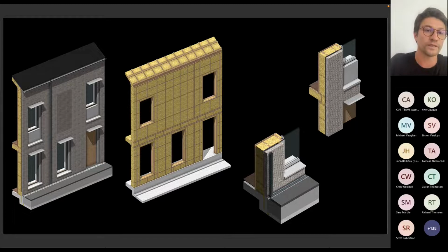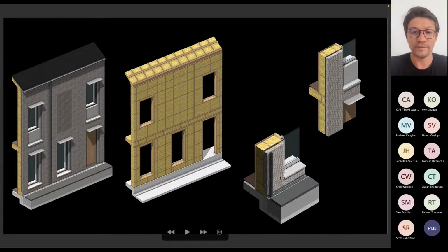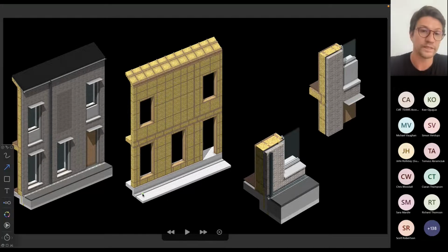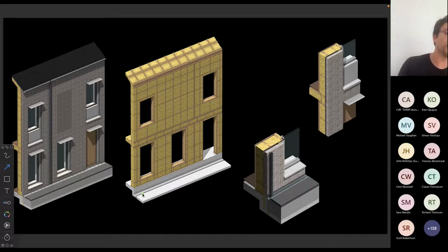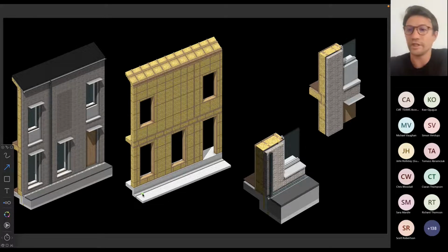And for these buildings, it really makes sense to have a masonry veneer building, as predominantly the main element here is availability of labor. In the UK, labor is available for these types of buildings, and there is no rush to get a scaffold up because it's only 2 or 3 floors. For a low-rise building below 18 meters, or probably it's going to be 11 meters soon, this is the way to go to achieve a brick facade.